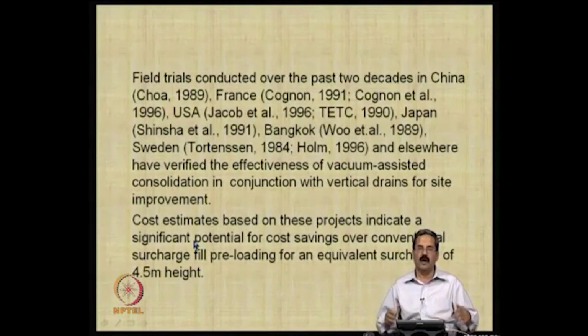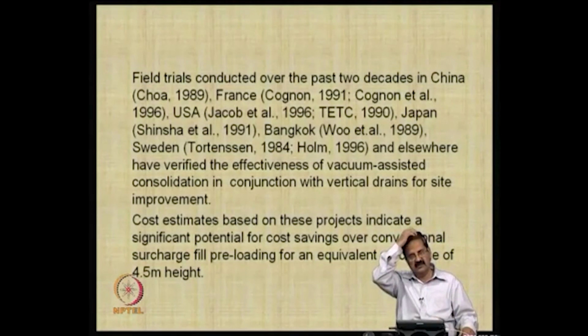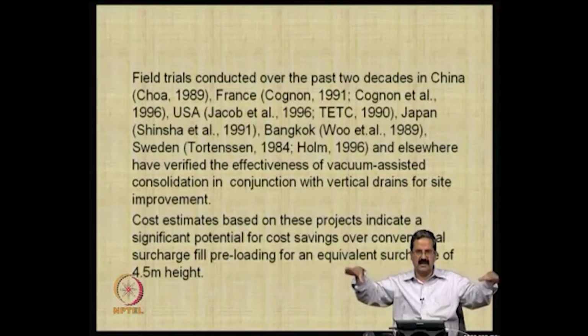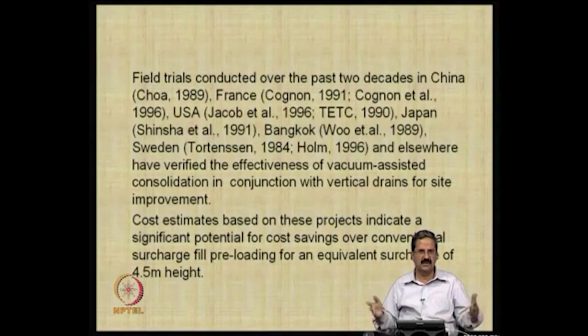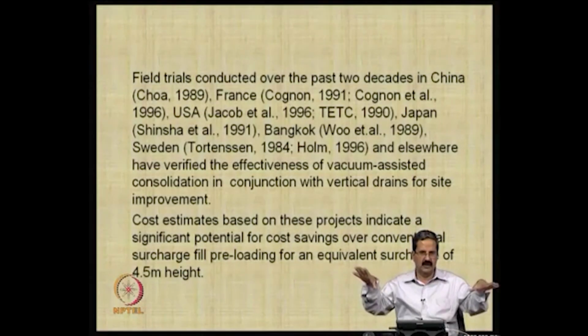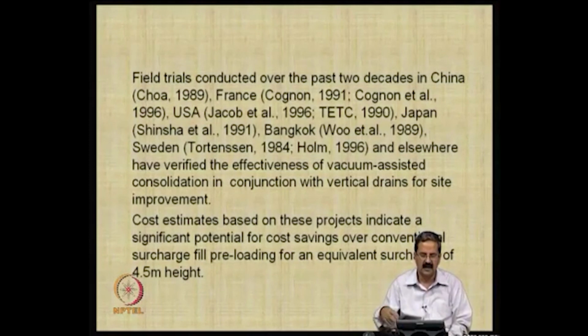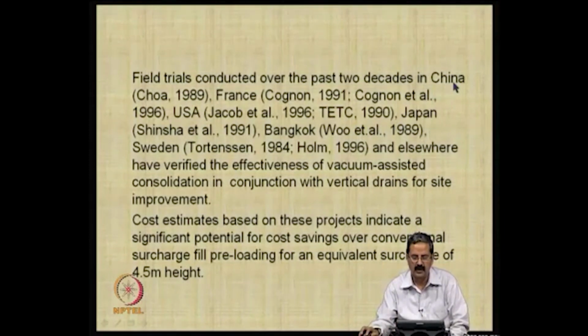In fact, you can even optimize the construction process itself. For the application of vacuum, once your sealing systems and everything are perfect, it just takes 2 days or so to stabilize. Exactly what you are doing is applying vacuum, and people have been doing a lot of field studies here. In China, France, Bangkok and many other places, they have verified the effectiveness of vacuum assisted consolidation in conjunction with vertical drains for site improvement. Cost estimates based on these projects indicate a significant potential for cost savings over conventional surcharge fill preloading for an equivalent height of 4.5 meters.